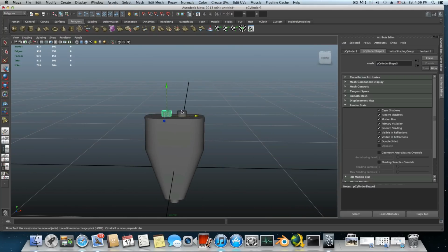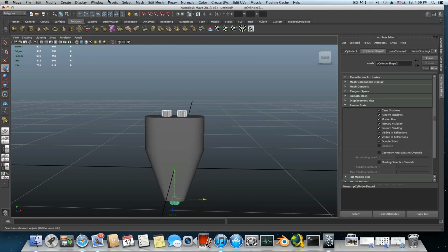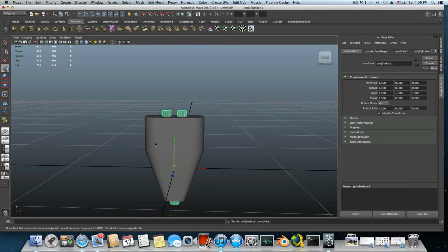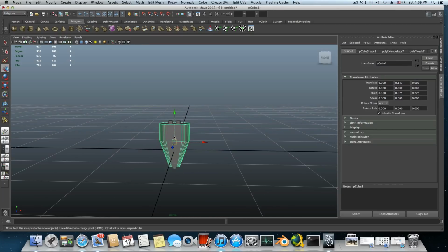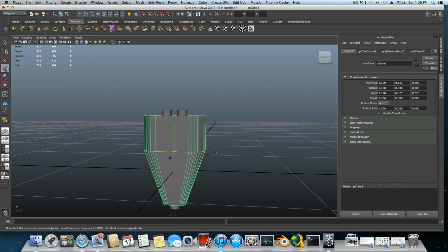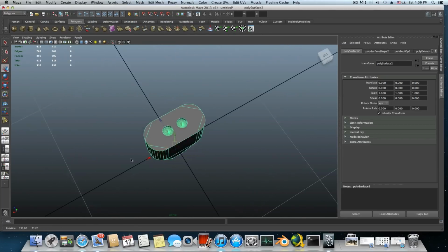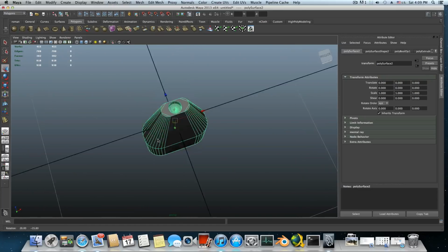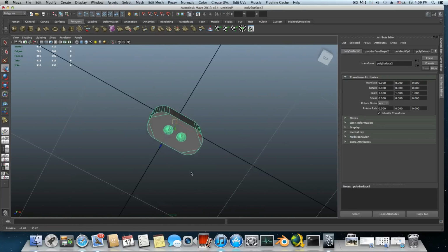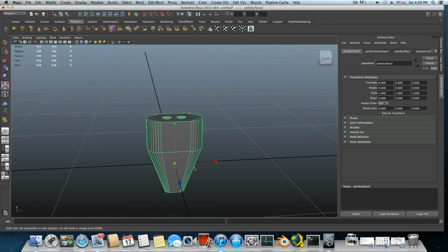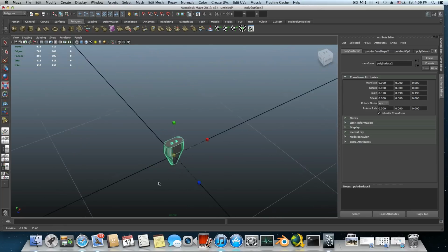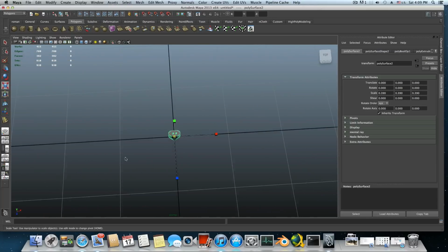And what I want you to do right now is to grab shift, grab all those pieces, okay, mesh, combine them like so. Basically what I'm doing, which I don't really like to do, but sometimes it's just easier, is first grab this big object, the main object here, shift select one of those, it will select them all if you combine them. Okay, you see they're all selected. Go over mesh, booleans, and difference. Now if you've done everything right, it should look like this, and that's great. Now we have this piece and it's ready, and we can also modify it, make it smaller, bigger, whatever. Okay, just make sure it's there.